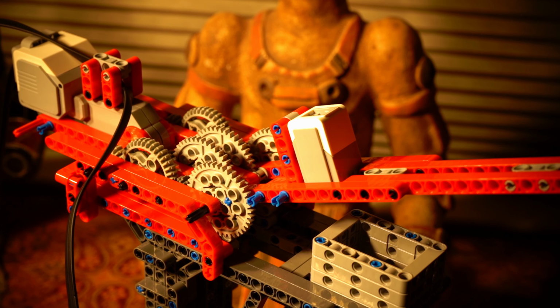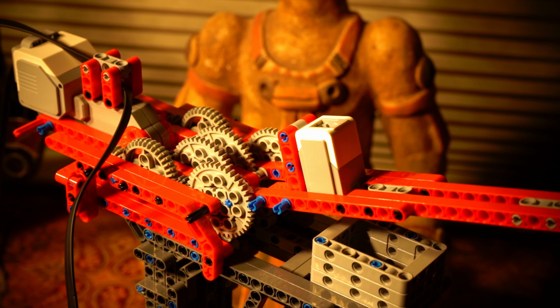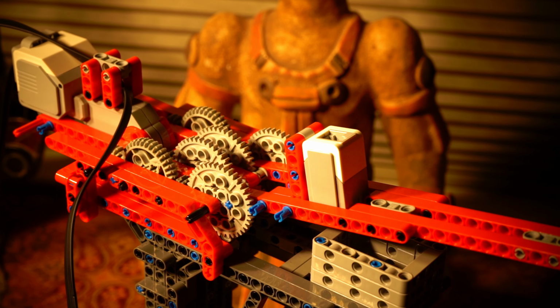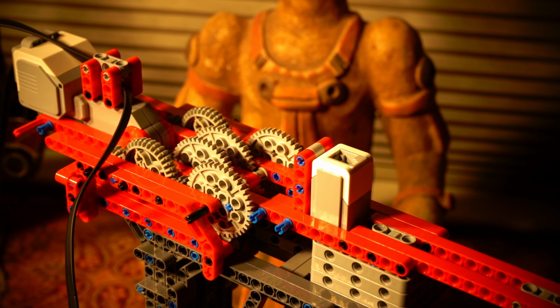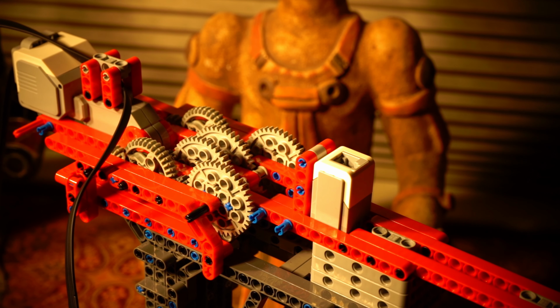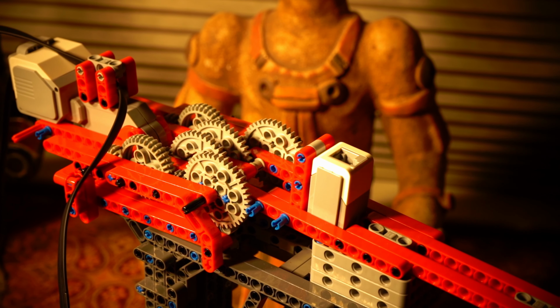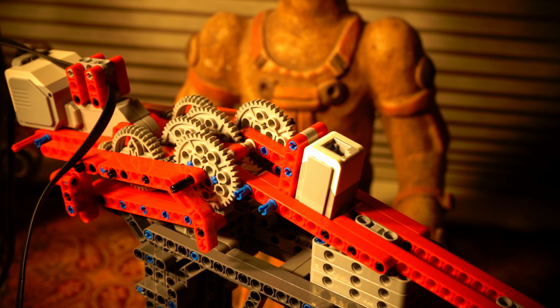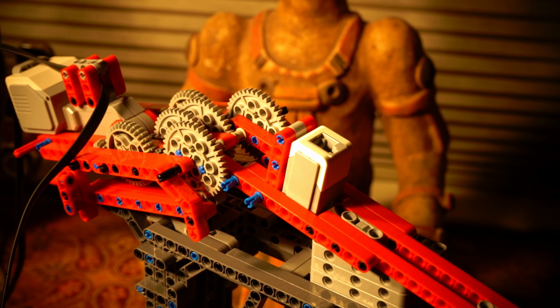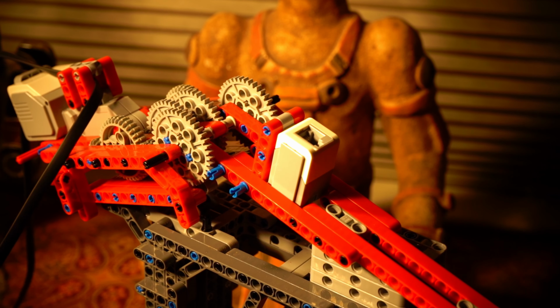For example, I've now disconnected the touch sensor so the EV3 brick won't know when the lift arm is horizontal. Rather than pausing and reversing, the servo motor now continues, forcing the crane from its perch and stripping a couple 8-tooth spur gears in the process. Runaway torque such as this should be avoided because it can damage LEGO gears and worse, LEGO servo motors.